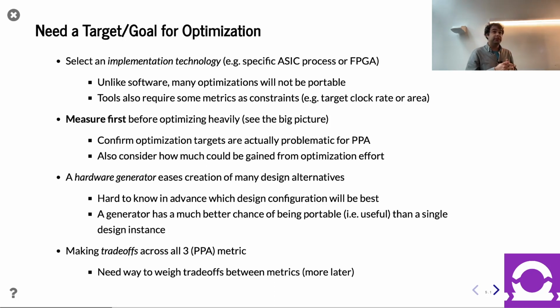If you study logic optimization, you will find that your target implementation topology really matters. And so, for example, maybe you want to reduce gate count. If you're on FPGA, for example, maybe you have only 5 input LUTs. Actually, you want to have more inputs per gate, right? So it really depends on technology. But in spite of that, there is some very cursory stuff inside of Chisel. It is not going to be as sophisticated as a full-fledged CAD tool, and it can't be, right? Because a full-fledged CAD tool, when it's running, knows what technology you're targeting. So it's going to inherently have more information.